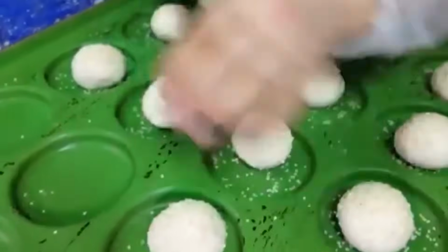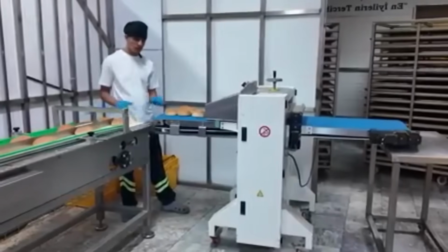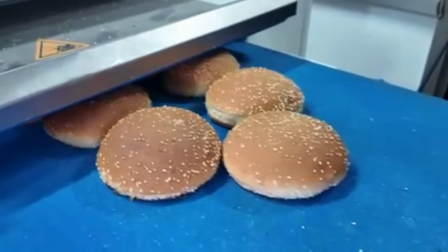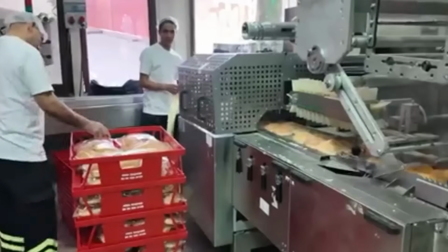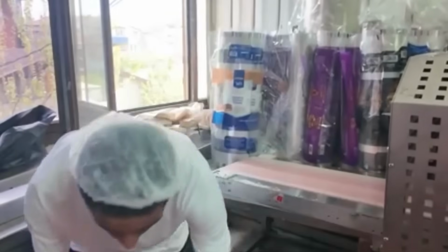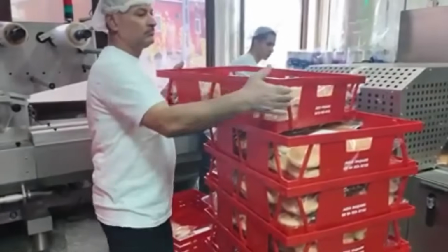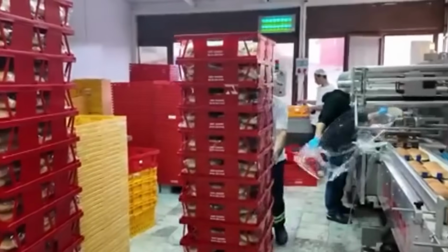The next step is bagging. A plastic bag is blown open by a quick burst of air and guided into place by forming horns. The sliced loaf drops in, and a closing device, either a twist tie, tamper band, or plastic clip, seals the bag in one motion. An inline printer stamps each bag with a code indicating date, time, production line, and batch number. The sealed loaf is then guided onto a secondary conveyor for inspection.